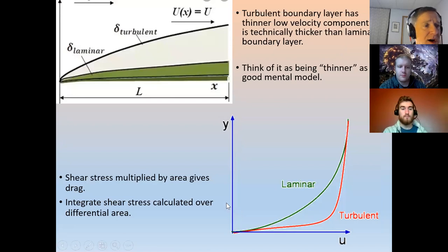And I don't mean to get all hung up about the laminar and turbulent boundary layer, but it's a designer's issue, because generally you want a turbulent boundary layer. That usually, if you're at high Reynolds number. If you're at low Reynolds number, you're not going to get a turbulent boundary layer anyway. So if something's going very slow, you don't want to have turbulators or rough up the bowling ball or any of that stuff, because all that does is add friction drag. But if you're going at Reynolds number over 2000, you want that.